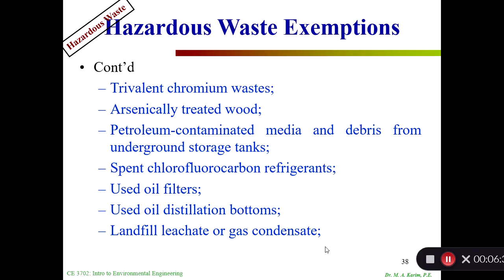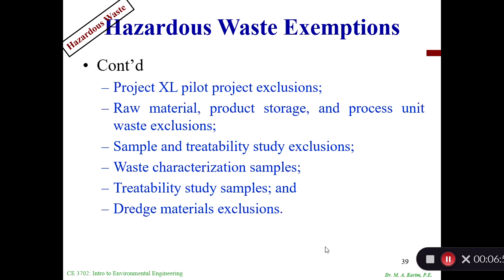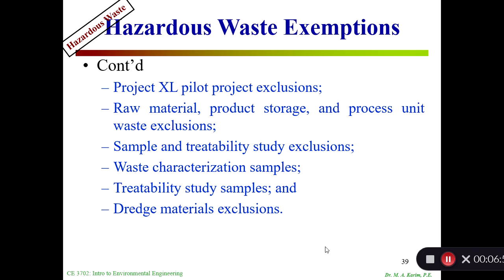They are exempted. Also trivalent chromium, arsenically treated wood that people most of the time use, petroleum-contaminated media and debris from underground storage tanks, spent chlorofluorocarbon refrigerants, used oil filters, used oil distillation bottoms, landfill leachate or gas condensate, then project XL pilot project exclusions, raw material product storage, process unit waste exclusions, sample and treatability study exclusions, waste characterization samples, treatability study samples, and carbon material exclusions. So these are the exemptions.